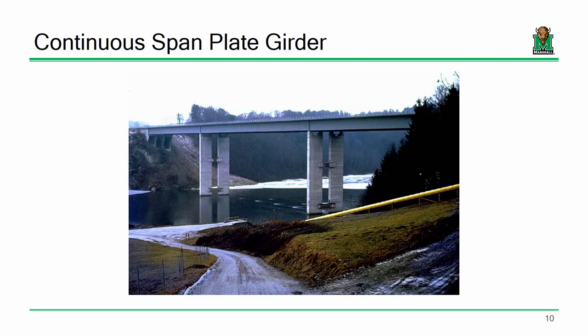Remember when you were drawing moment diagrams, you might have heard the term, smiley face positive, frowny face negative. Remember that? That would tell you the sign convention for your moments. Well, there are instances on this beam where if we apply load to it, as it's got load right now, some of these sections, particularly the sections between those piers, are going to be bending positively. Across the piers, though, like right here or right here, they're going to want to bend negatively. And that's really important to consider because the material can behave fundamentally differently.